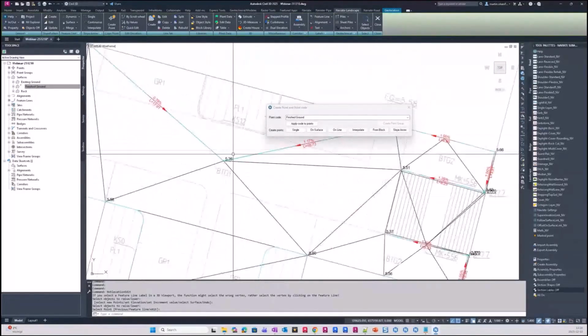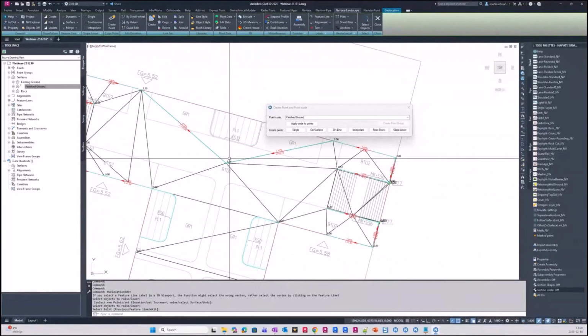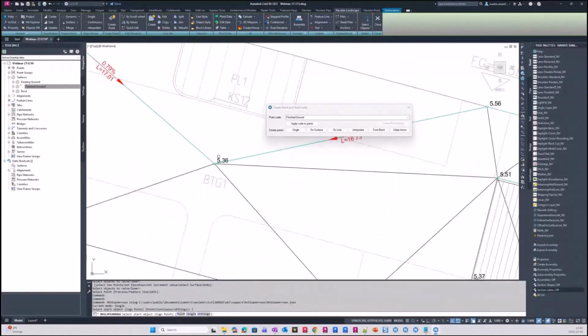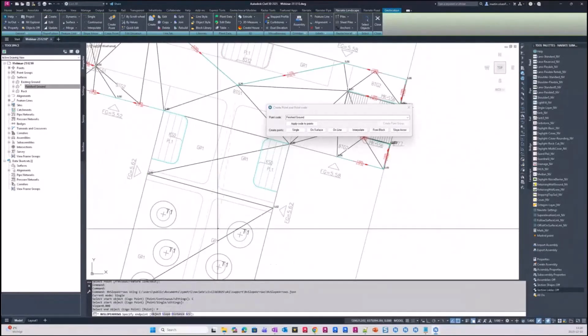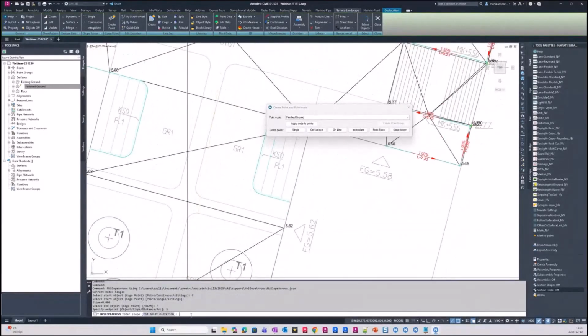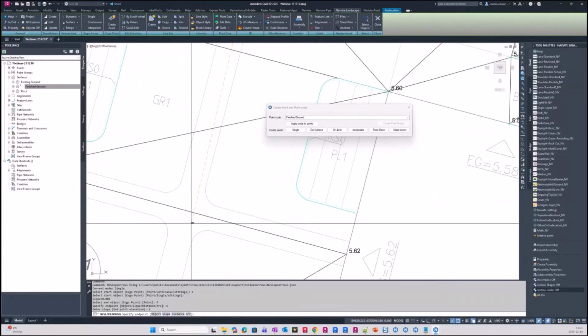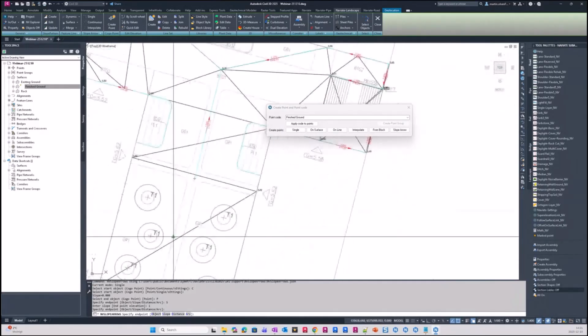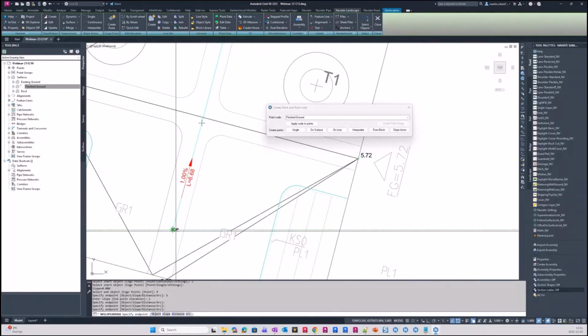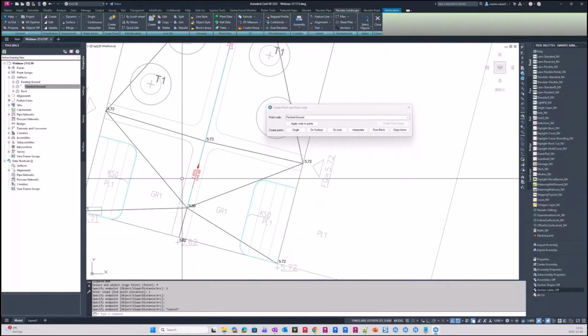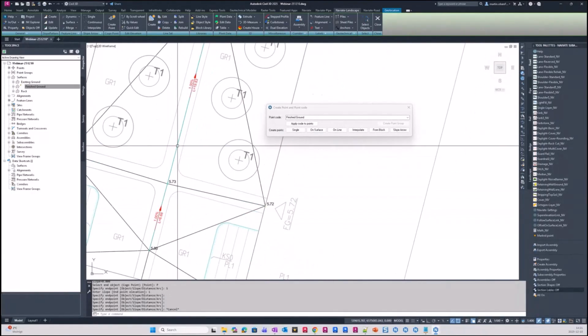And if I want to move or create points continuous, I use this continuous functionality instead. I can do the same thing here. I can choose a point to start from. So if I want to start from this point, just pick that one, and then I can connect to another, or I can pick point, edit the slope if I want to. I pick a positive 1 slope instead, and then just do a continuous line here. And when I finish that one, I can see the point elevation heights.